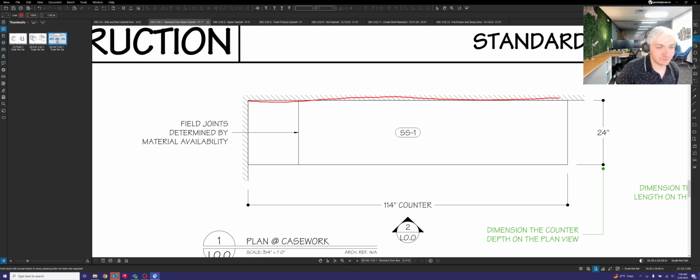And this is very, very dramatic, but it can vary slightly. So it might actually look something like this. And if that's the case, you really do need those nailers or that shim there behind the cabinet to be able to make sure that that cabinet is staying flush with the front edge of your countertop like that.